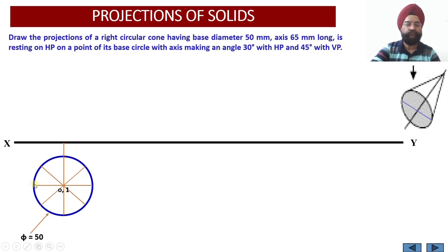And having drawn all these, now we are going to join all the diagonals. Wherever all these diagonals join, we are going to get the location of the axis point. So two axis points have been located, O and 1. You see, O is the apex point for the axis, 1 is the bottom point for the axis. Similarly, you see 8 points we have listed over there, A, B, C, D, E, F, G, H. So this completes our top view projection of the cone.